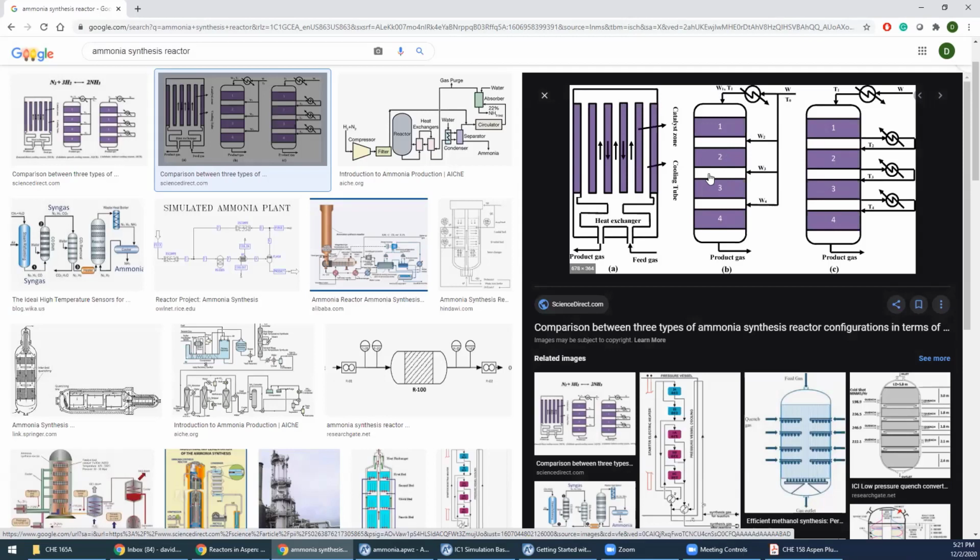Alternatively, you can have hot shots. So if this is an endothermic process going through this bed, and you put in a hot feed to keep the temperature up, to keep conversion higher, selectivity, or whatever your specific thing you're looking at is, then you can keep the bed warm by putting in warm reactants to get some okay products. And then it just goes through the bed like that.